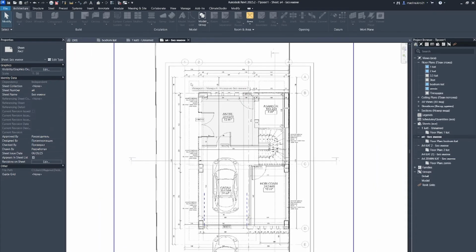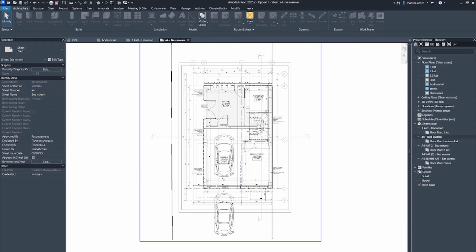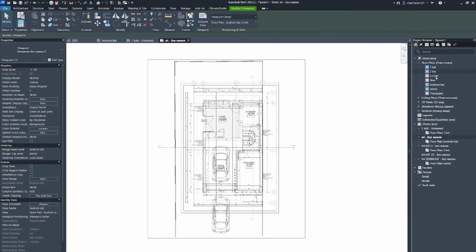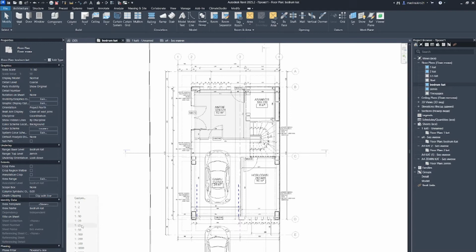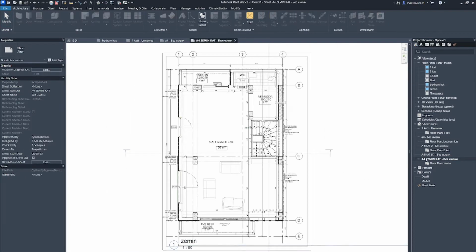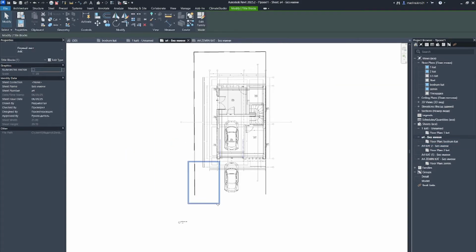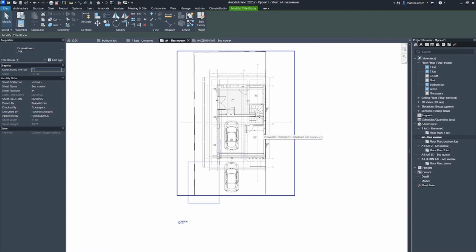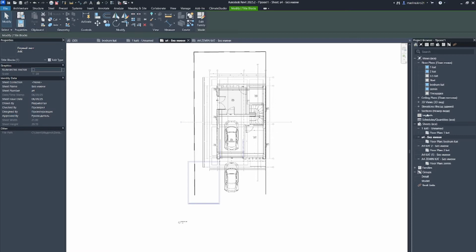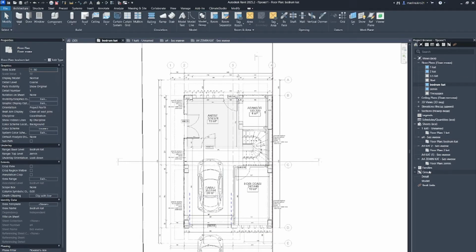So, as you understand, first of all, we make sure of the paper format which we have. This one is A4 for me, that's why I used 1:50. If I change here to 1:20, which is actually bigger, as you can see my writing becomes so small, and then I open this one. As you can see, my scale changes and the paper becomes small to show all of this project. So be careful, please. For now I don't change, I stay at 1 divided by 50.